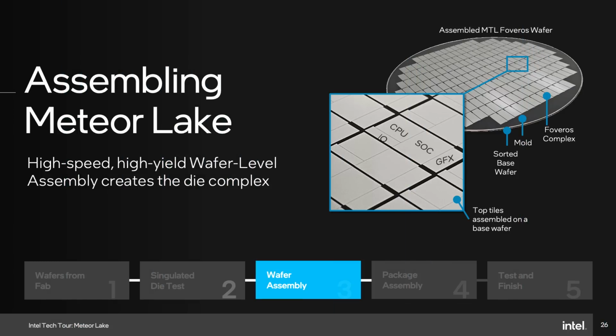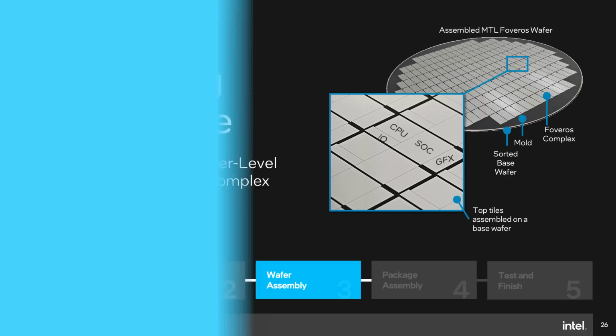After we sort them or singulated die test them, that's where we move to the first step of the Foveros operations. This is what we call wafer assembly. This was the major new capability that we had to put in. Obviously, we have to have tools, equipment, and processes to take the top die and stack them to the bottom die. The bottom die, or the base die, is in wafer form when we do that.